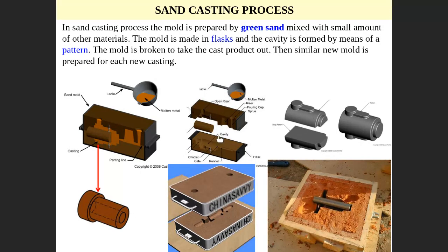And finally, you assemble this kind of mold, then your cavity will be created. So this is what we call the pattern, right? When you put the pattern in the sand, if it is only sand, it doesn't work. You must add some additive so it can become plastic. You can plastically deform it to create the cavity, right? So you put it here, you create the cavity up and down.